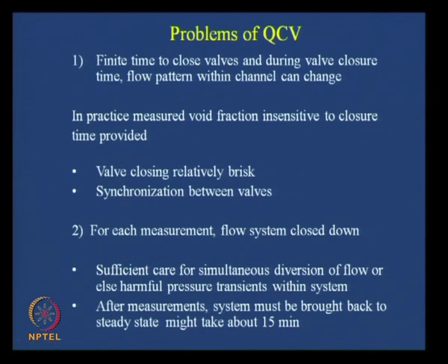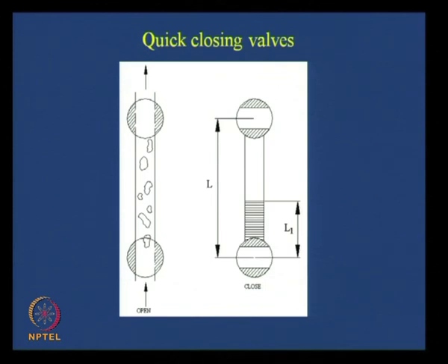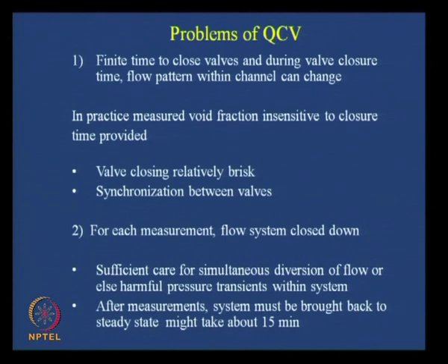See, when you are practicing, what are you doing? You are actually stopping the flow. You are closing the valves, you are actually stopping the flow. Now, you have to keep two things in mind. This flow then has to be diverted through some other portion, otherwise it will accumulate and it will create a large amount of transient pressure, maybe the blow down of this test section. So, this firstly has to be kept in mind. The other thing is, or else you can simply stop the flow. You can just close the valve, close pumps, everything, you can stop the flow.